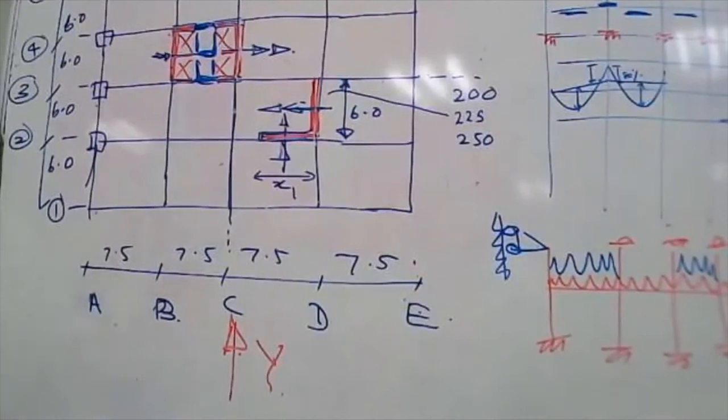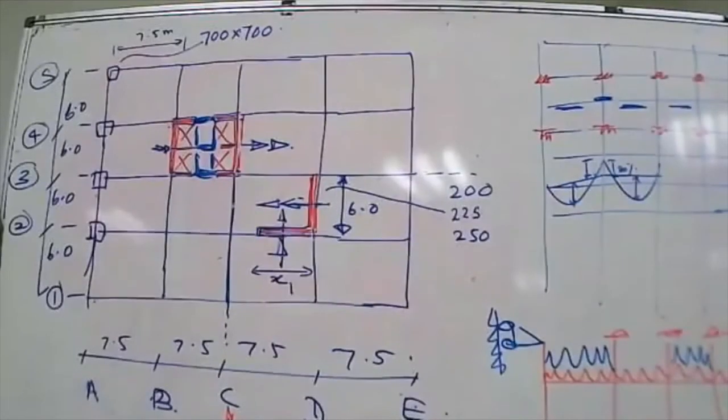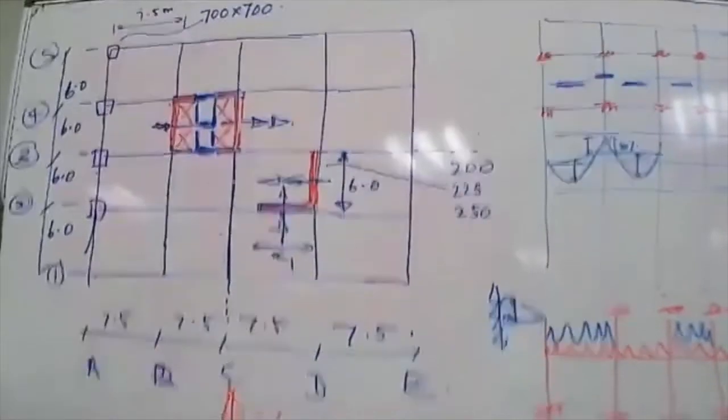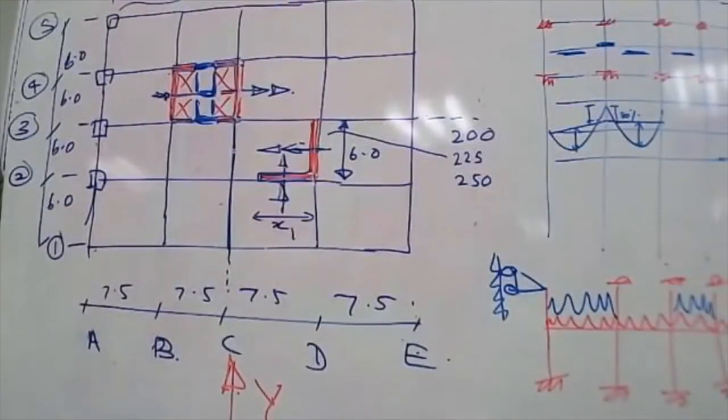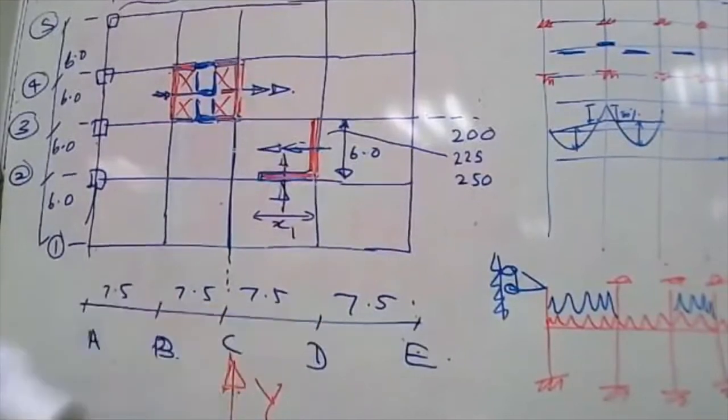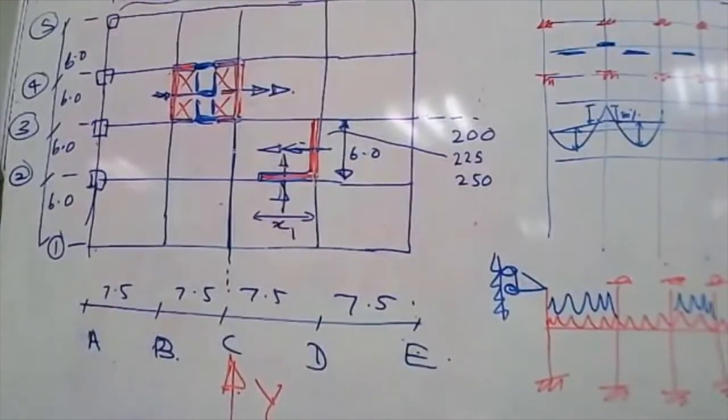Now we are approaching 8:30, and I think we can take only about one or two more questions. So basically, once you know the bending moments and shear forces, you can design the reinforcement in the frames and the columns from this frame analysis. The load transferred onto the column at each floor can be determined by using the subframe.